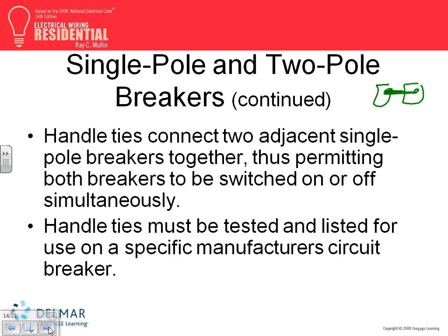So that's the little device from the other day, the little plug things. It has to be an approved method. The wire part that we used to do, tying them together, is not an approved method. The reason behind this, my understanding, and I could be completely wrong, is they want them to trip, both of them at the same time, when you open them.